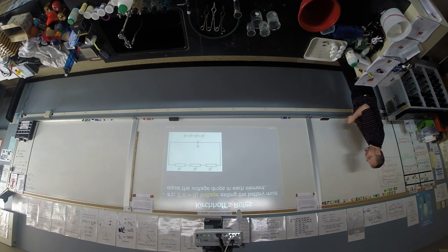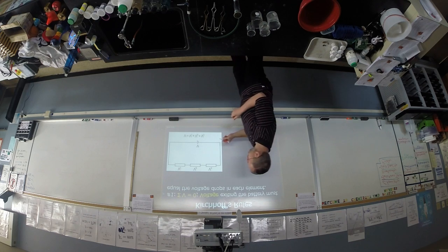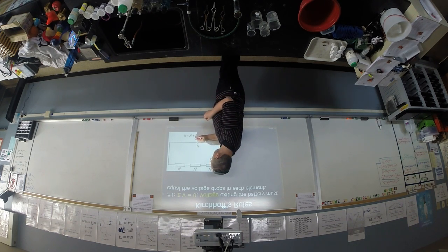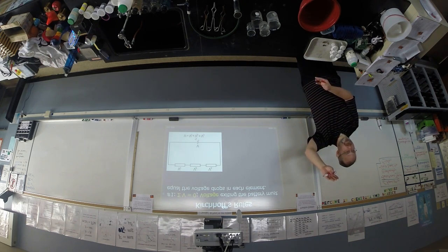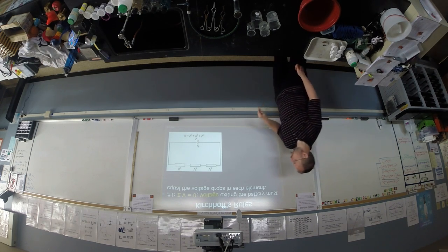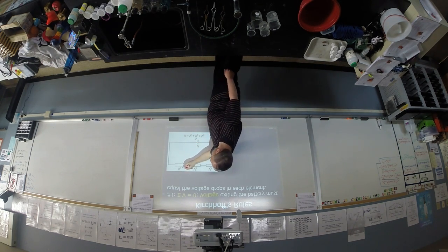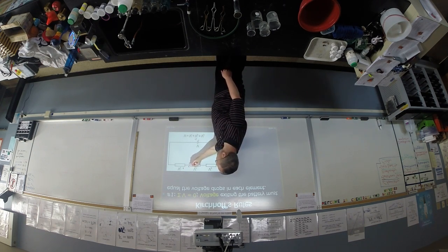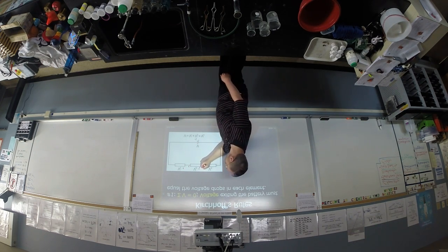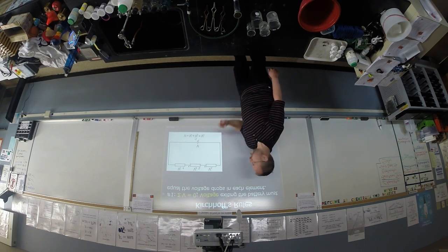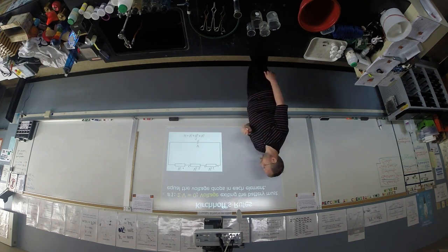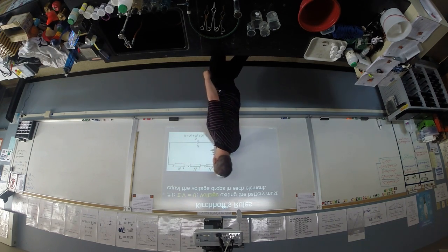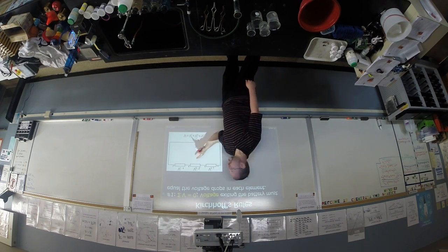So by example, let's just go with our simple 12-volt battery. If a 12-volt battery is 12 volts, that means it's plus 12 on one side and 0 on the other. It has 12 volts of potential. The cliff is 12 volts high. The water's going over. So if you got a 12-volt battery and you lose 4 here, that means there's 8 left. And you lose 2 here, that means there's 6 left. Which means this V3 better be what? 6. So it has to have 0 left. Okay. It has to go in with 12. Go into the devices with 12, come out of the devices with